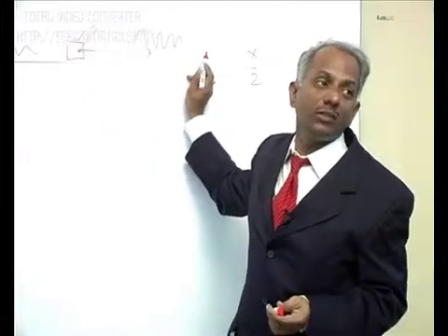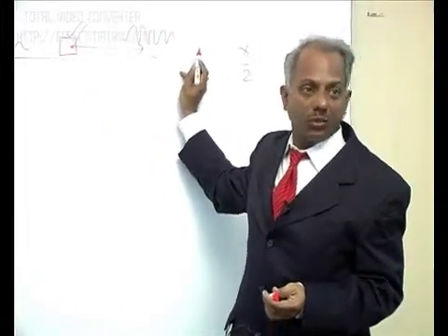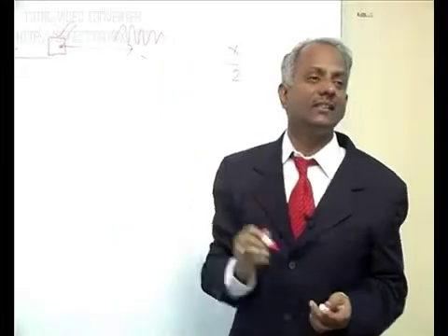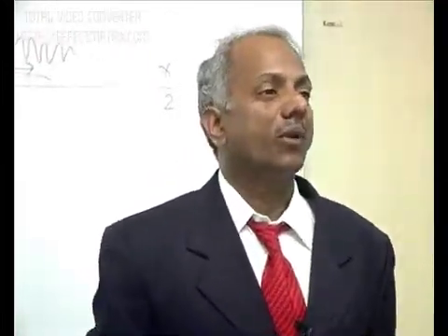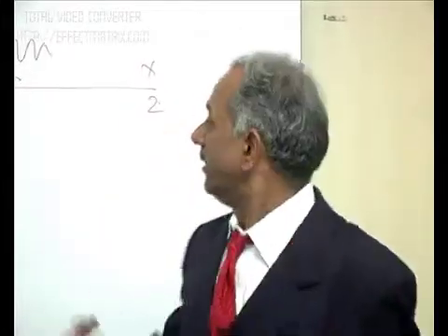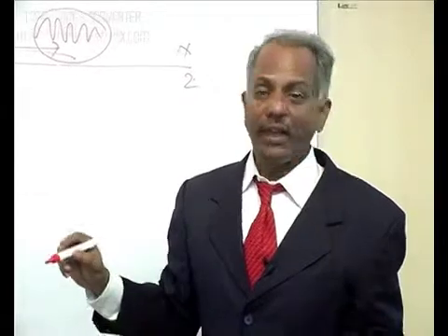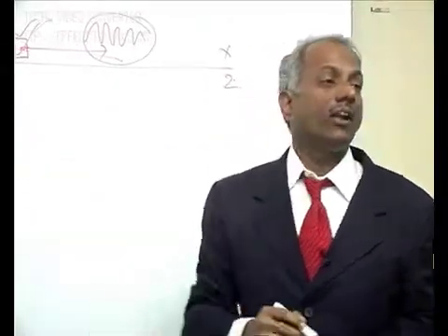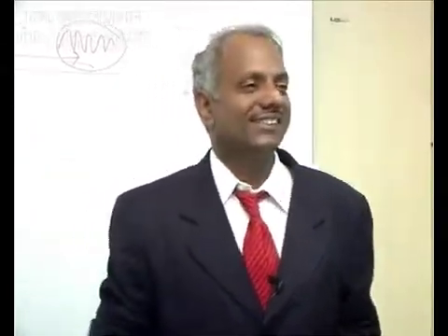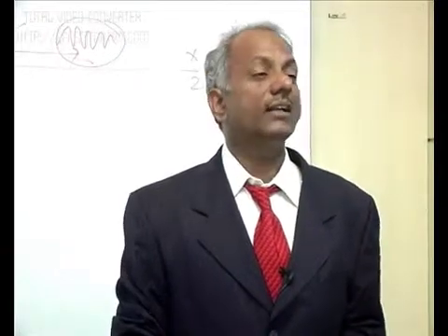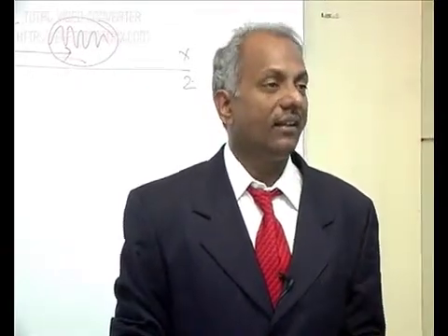For an observer who is getting the object close to him, there is an increase in the frequency. This is known as Doppler shift. So by determining the change in the frequency of the received signal, we can find out the velocity of the target. This is exactly what is practiced in radar systems.